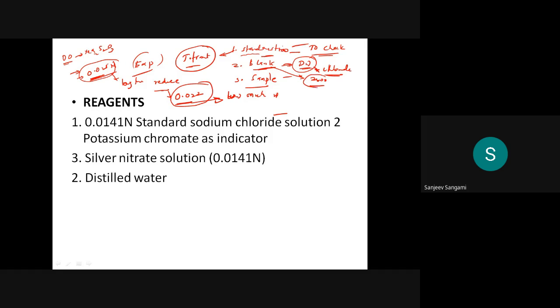But in some distilled water preparation plants, a slight trace of chloride will exist even in distilled water. If you use that distilled water for your experiment, the chloride is going to accumulate, so we always have to deduct it.